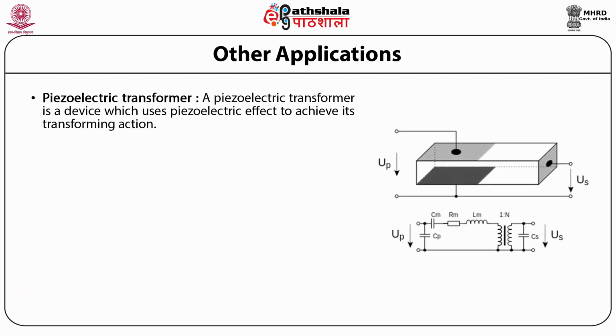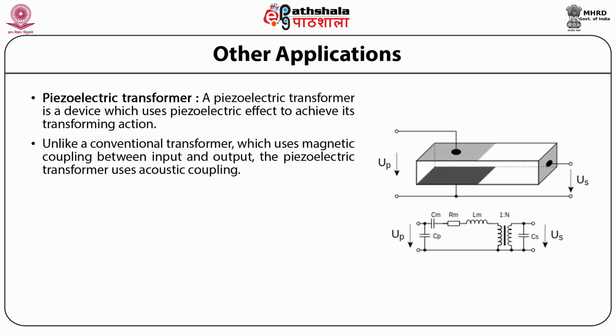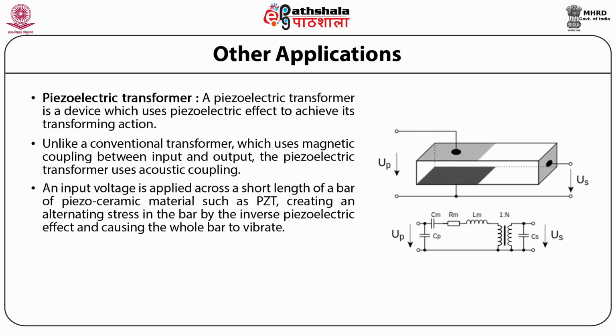Piezoelectric transformers. When input and output terminals are fabricated on a piezo device and input-output voltage is changed through the vibration energy transfer, the device is called a piezoelectric transformer. Unlike a conventional transformer, which uses the magnetic coupling between the input and the output, the piezoelectric transformer uses the acoustic coupling.